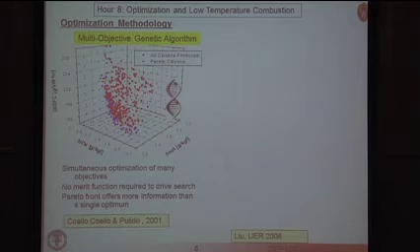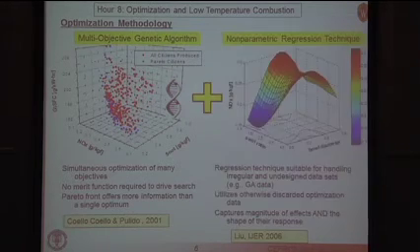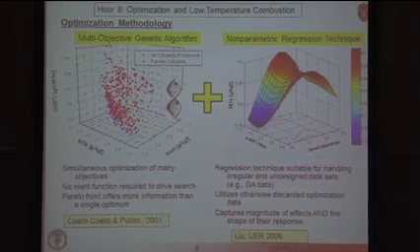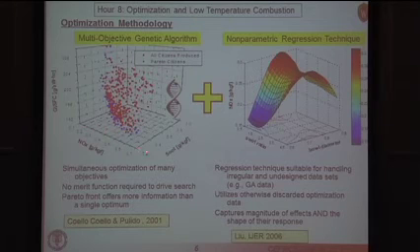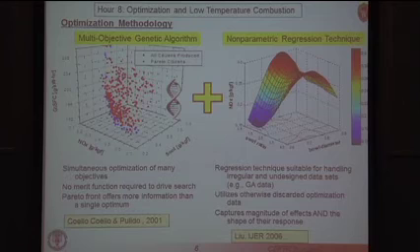To get further than that, we can take all of that data and apply a response surface method to that data. For example, if we were just interested in NOx, we'd take all this data and plot NOx versus parameters of interest in the simulation. It might be swirl ratio or piston bowl diameter, whatever it is. And we'll find, again, that we can minimize NOx by operating at a certain place in this map. So the idea is to essentially combine the genetic algorithm with some sort of regression technique to look at the variables themselves.